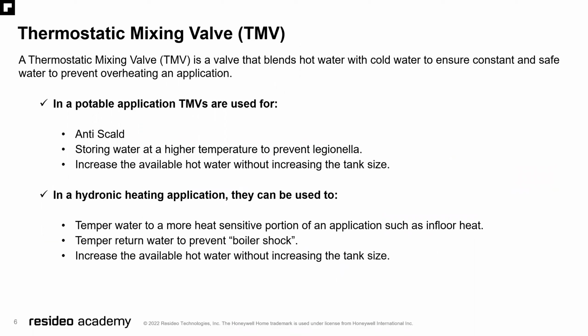A thermostatic mixing valve, TMV, is a valve that blends hot water with cold water to ensure constant and safe water temperature to prevent overheating in an application. In a potable application, TMVs are used for anti-scald, storing water at a higher temperature to prevent Legionella, and to increase the available hot water without increasing the tank size.